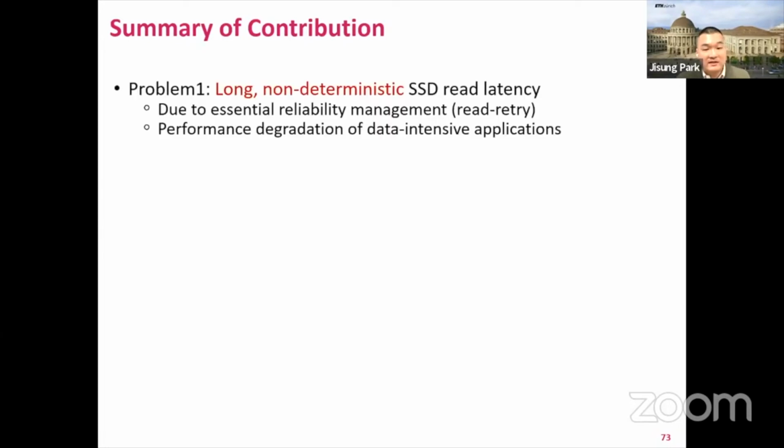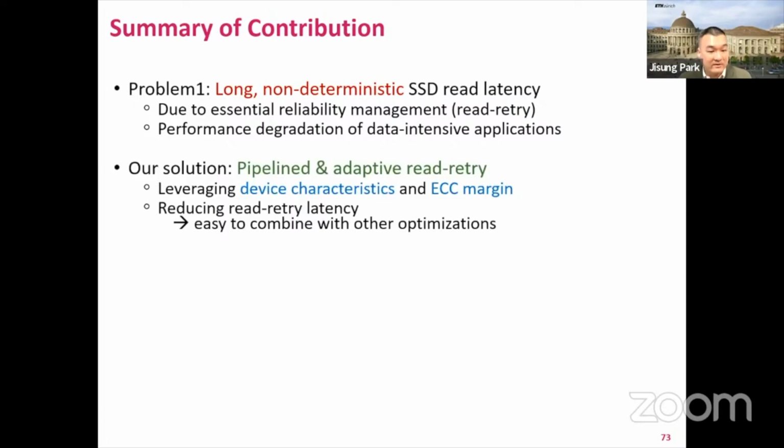Okay, let me conclude today's lecture with a summary of contributions. The first work tackles the long and nondeterministic SSD read latency due to an essential reliability management scheme in modern SSDs called Read-Retry, which can significantly degrade the performance of data-intensive applications. So we propose a pipelined and adaptive read-retry that reduces read-retry latency by leveraging read-retry characteristics of NAND flash memory and the ECC margin existing in modern SSDs.